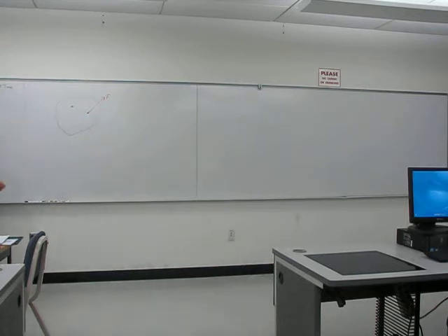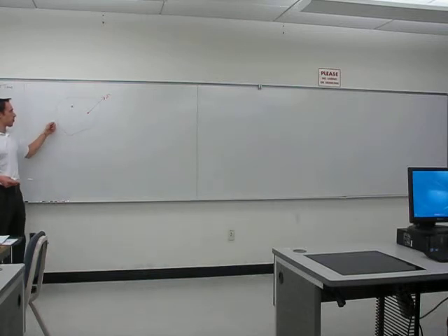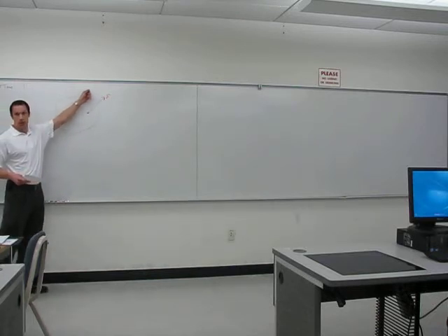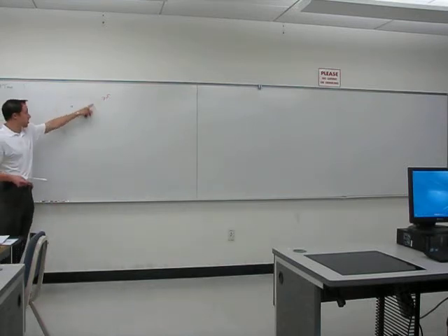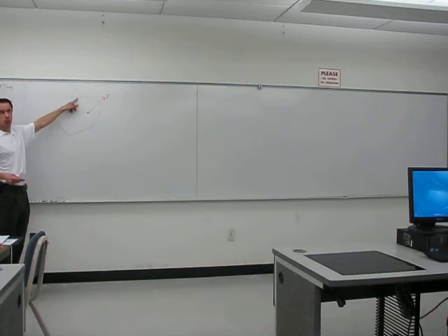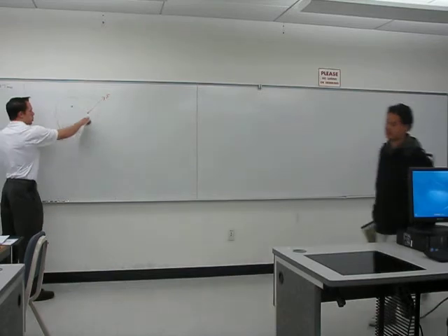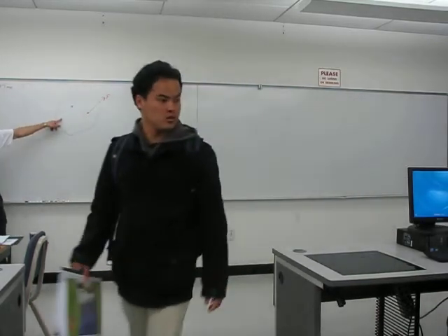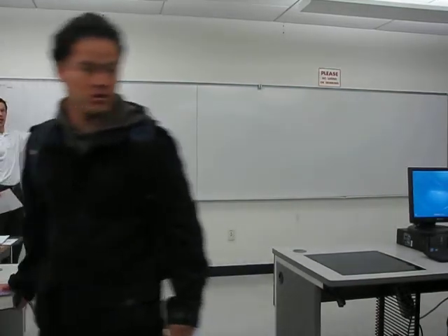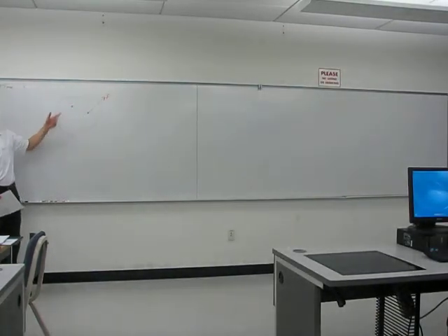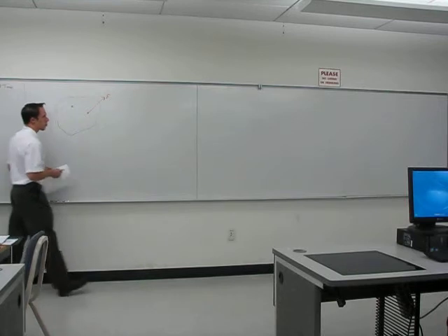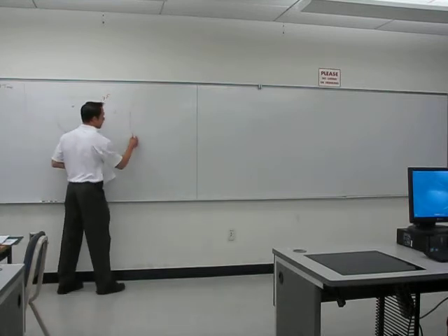So we said that what we can do is we can essentially apply two forces, same magnitude, equal and opposite directions at this new point. One of those forces would be representing the movement or the reapplication of this force to the new point, and then the original force plus the other one would form a force couple, which we could then create a force couple vector, moment vector, that would be at that point as well. And we ended up with a picture that looked like this.